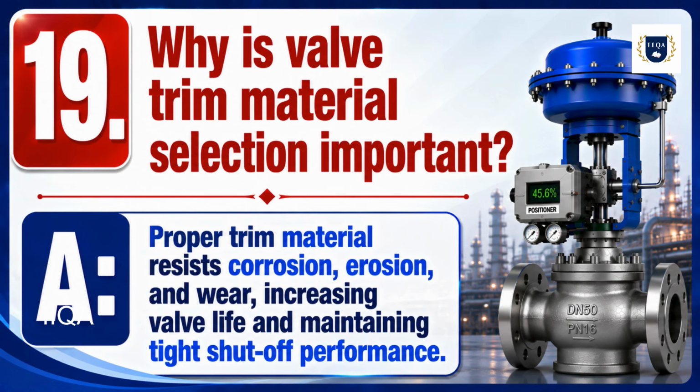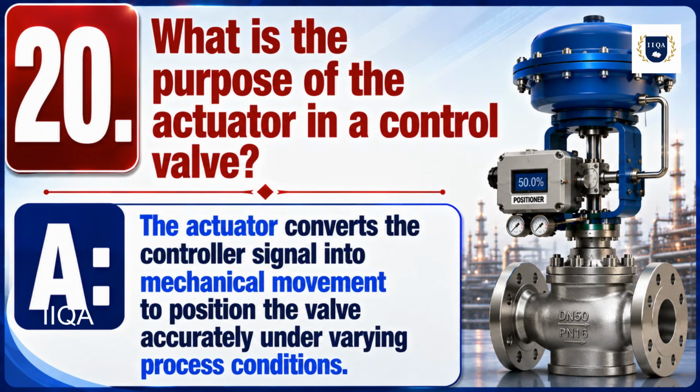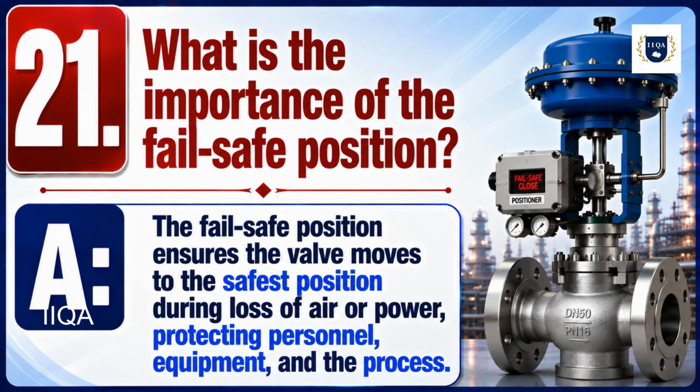19. Why is valve trim material selection important? Proper trim material resists corrosion, erosion, and wear, increasing valve life and maintaining tight shut-off performance. 20. What is the purpose of the actuator in a control valve? The actuator converts the controller signal into mechanical movement to position the valve accurately under varying process conditions.